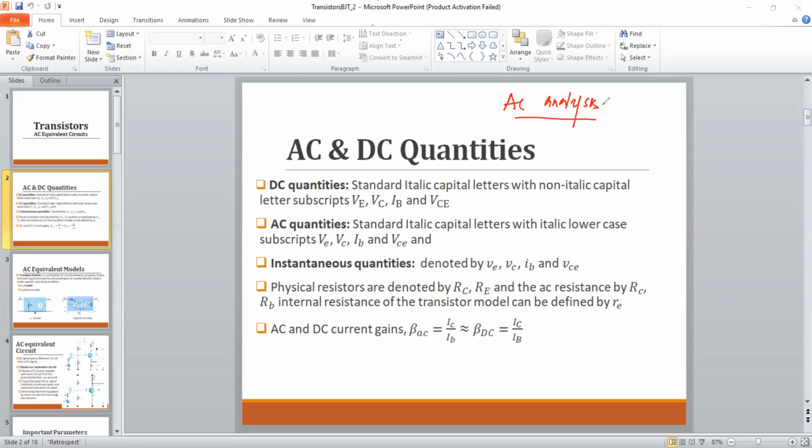So how do we get the DC load line? We follow a couple of steps. First, we need to remove the impact of capacitors and inductors, because now we are dealing with a DC circuit. So we replace the capacitors with an open circuit element and inductors with a short circuit element, and we simplify the circuit to a DC equivalent model. For this DC equivalent model, we don't have capacitors and inductors, which is identified as the DC equivalent model of this particular transistor circuit configuration.